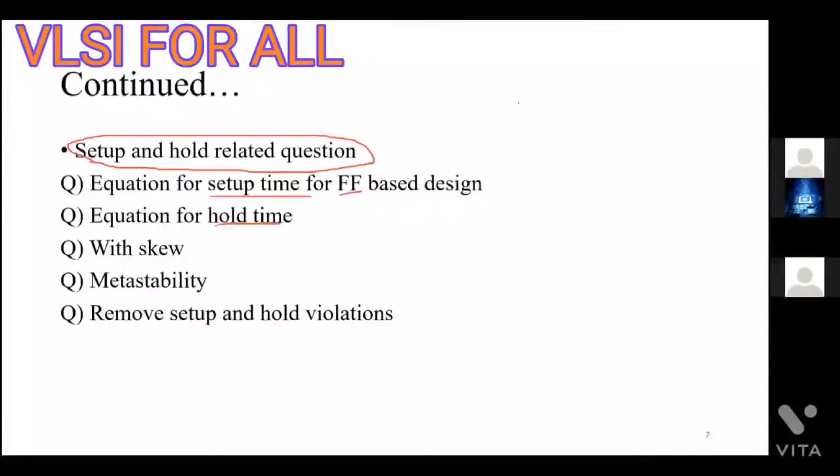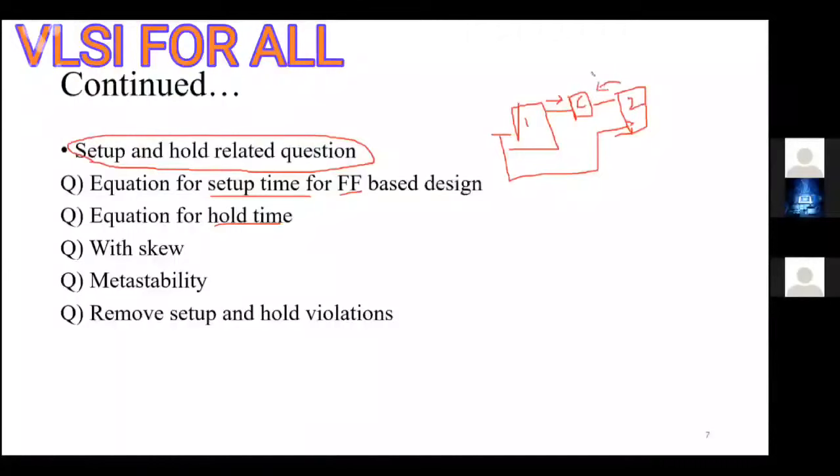If there are two flip-flops and a combinational circuit in between, both connected to some clock, and there is some output coming from the first flip-flop, it needs to reach the second flip-flop before the clock edge, and it should reach before the time TS. This is known as setup time.